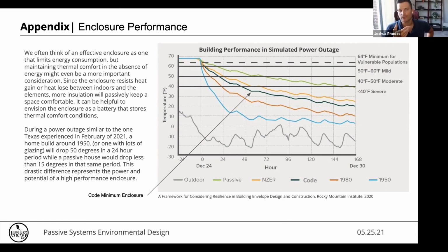Yeah, so the majority of buildings in Texas have smart meters and have the ability to remote connect and disconnect. The thing is, the back end that services that can only handle a few thousand per day. And so if we wanted to adequately roll blackouts using meters, we would have needed to do millions per day in order to keep people's outages at an hour length or 45-minute length or whatever they were promising they would be. So technically we have the potential to do that, but we don't have the system in place that would actually allow that to happen. It's basically like we would be trying to do it with dial-up, and you really need gigabit internet to do that type of thing. Got it.